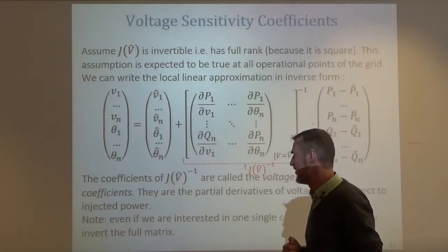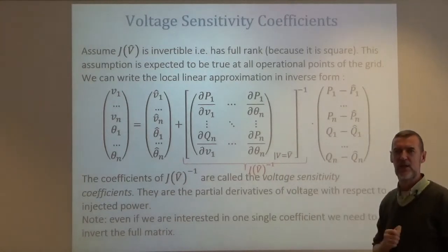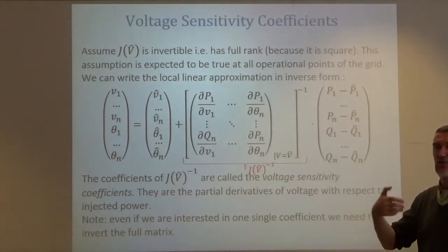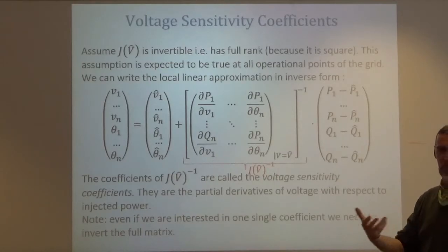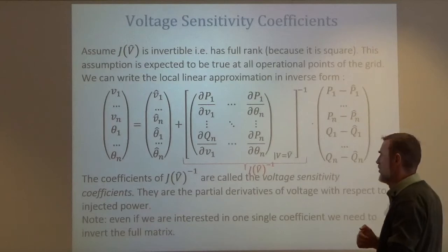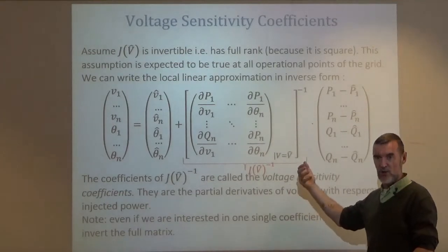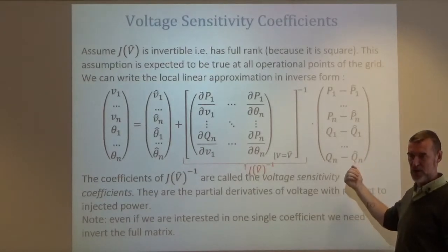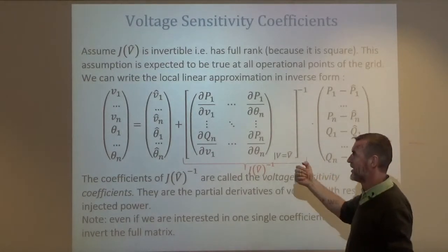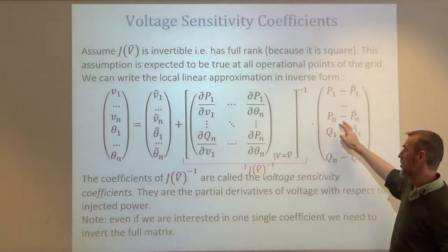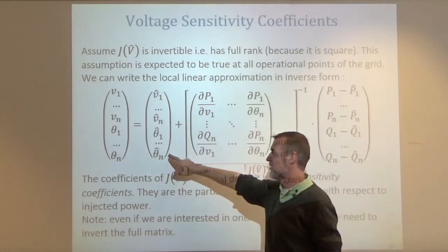And to prevent it, we would like to curtail the power injections, or better than curtailing, if you have a battery in your grid, you might increase the load absorption by asking your battery to consume that power which comes from the solar PVs. By how much should you instruct the battery to absorb? Well, if you know what is called the voltage sensitivity coefficient, that says the delta V over delta P. What is the impact of a change in power injection on V, right?